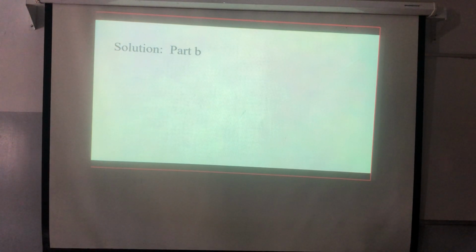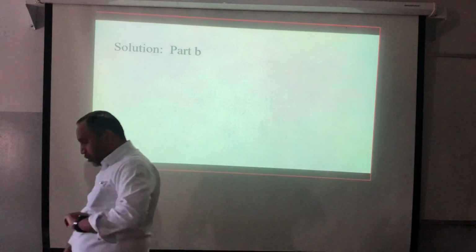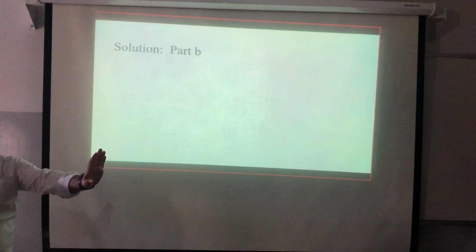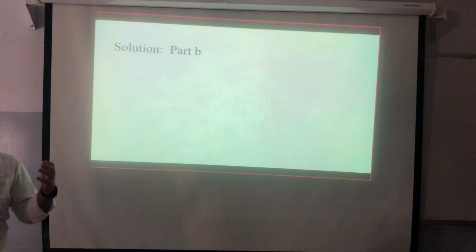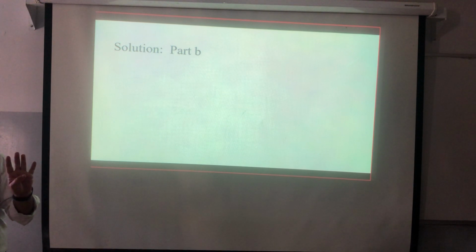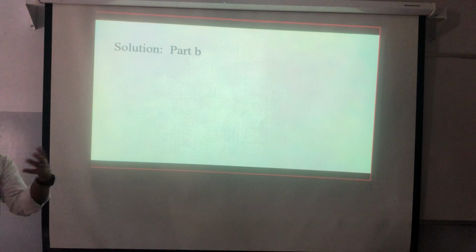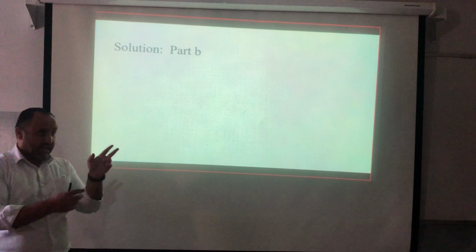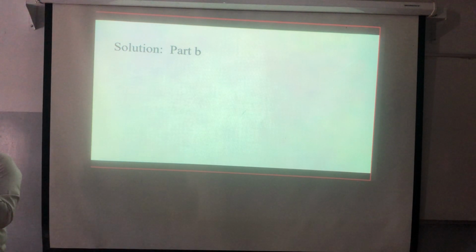Now, the second one was what? I need to find the resistance that I should add to the armature circuit such that the machine would be at the hold position. So omega equal to 0. So the back EMF, EA, equal to 0. The back EMF is K phi omega. If omega equals 0, then the induced voltage will equal 0. If I need to generate a voltage, I need the flux and rotation. So, in this case, V is equal Ri. So R total is equal V over I.